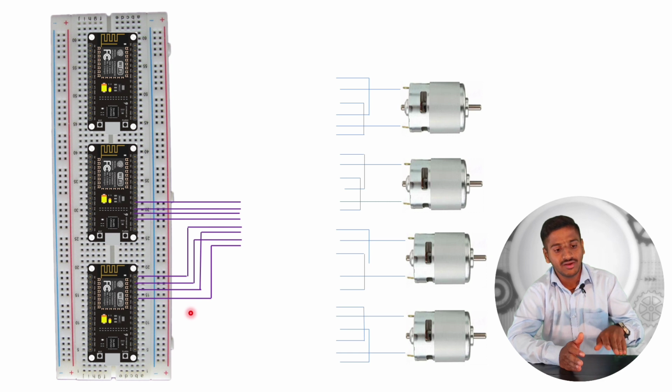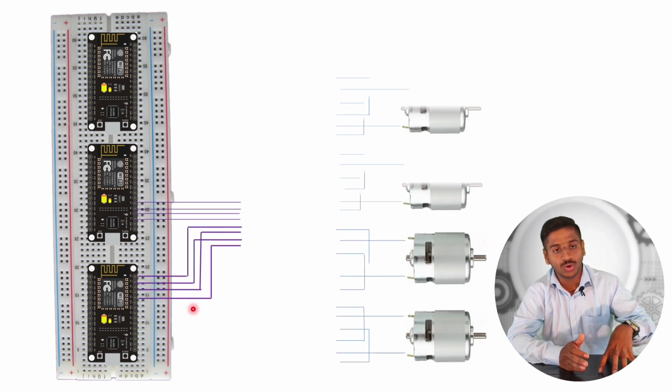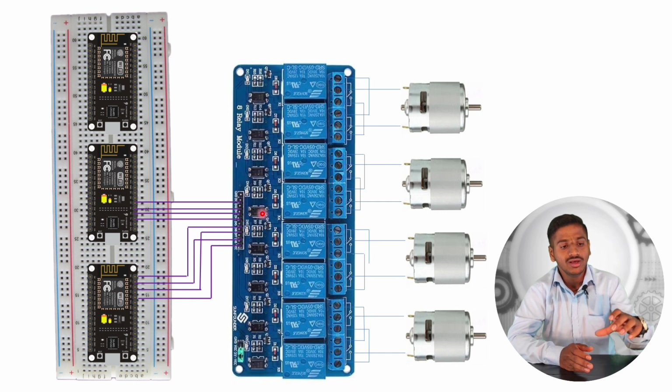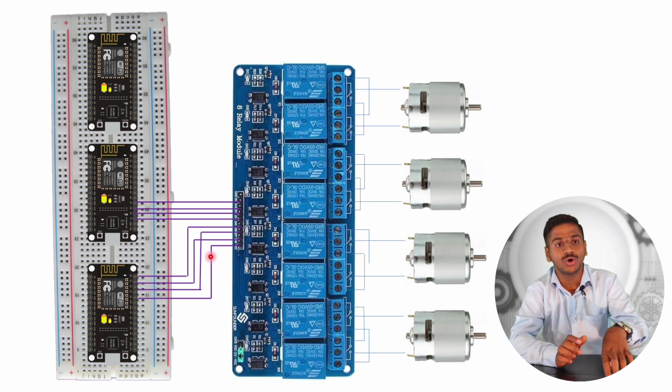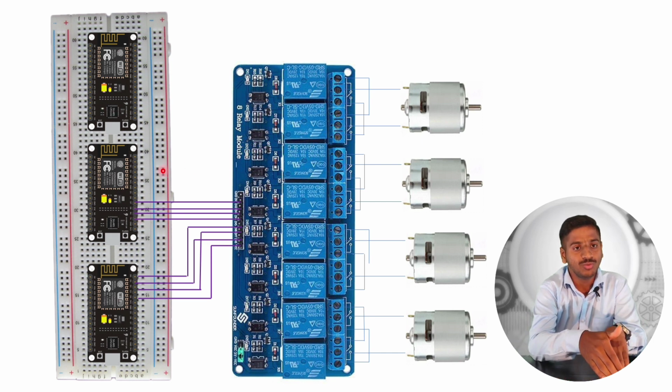So you can see there, when I go from the controller to the next up, the relay module, there is an 8 channel relay placed, where we have connected all the drawer motors to this particular 8 channel relay. The 4 pins of the 8 channel relay are connected to the first NodeMCU, so that 2 motors, D1 and D2, are controlled by this starting 4 channel relay.